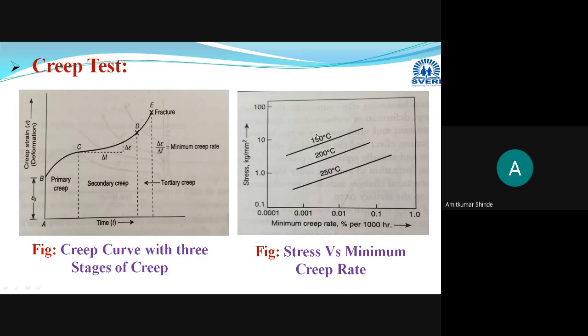Due to the higher temperature, even with minimum stress you will get the desired creep rate. When you increase the temperature with lower stress values, you can achieve that creep rate. So this is the effect of stress and temperature on the minimum creep rate.